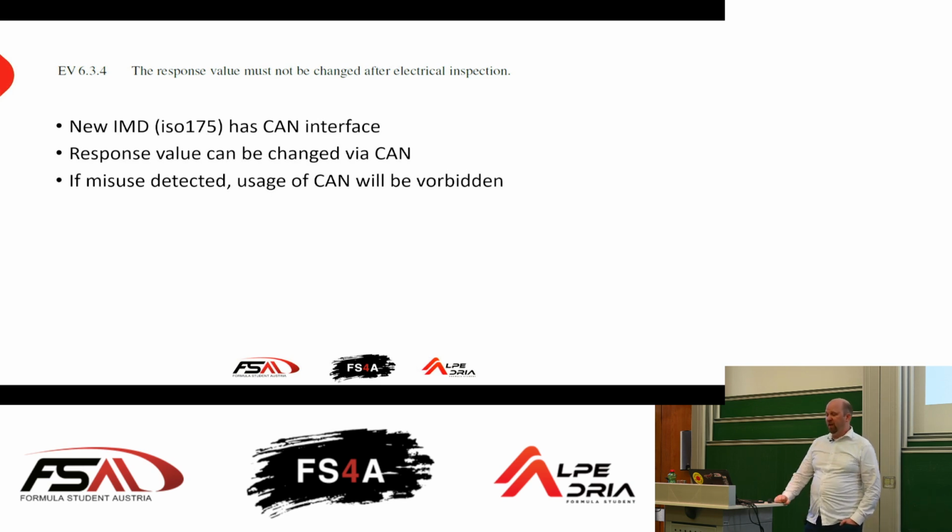There's a new vendor, IMD, the ISO 175. Quite a nice part. It has a CAN interface. With the CAN interface, you can read out the voltages and the isolation resistance. Really nice if you use it. With this CAN interface, you can also change the response value.